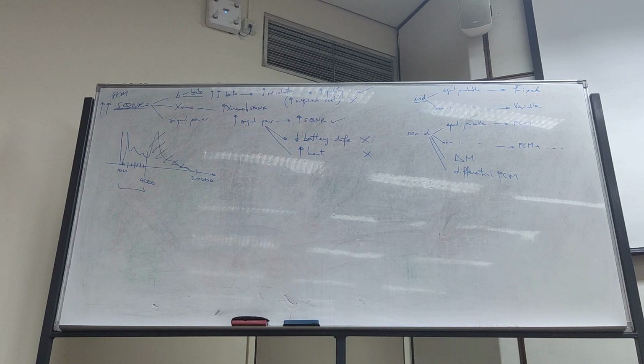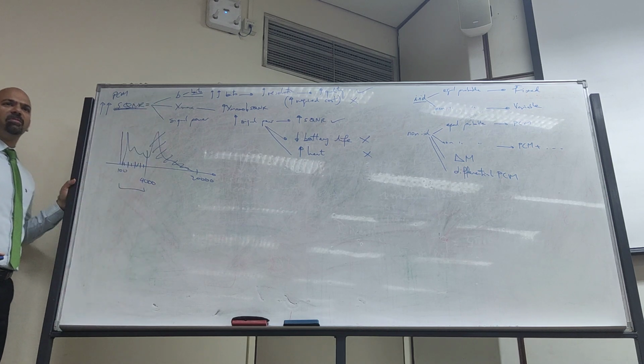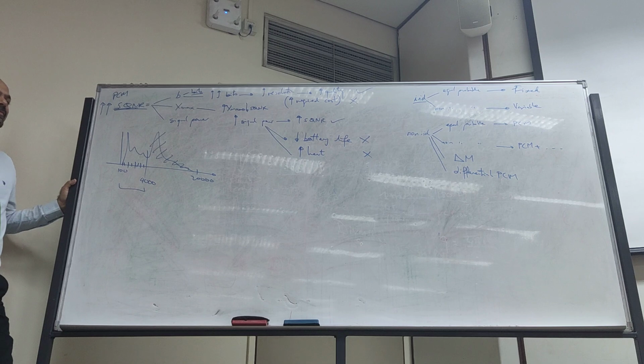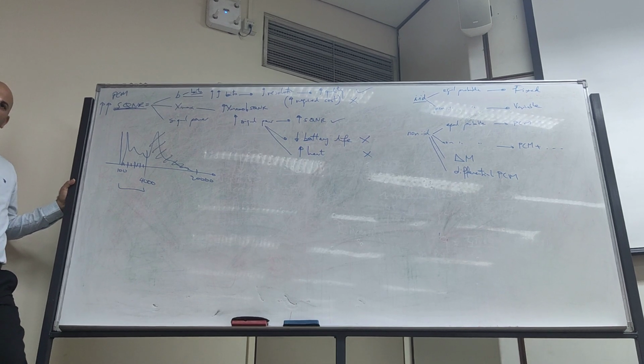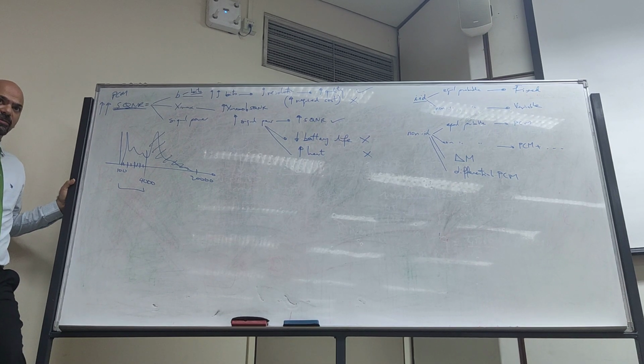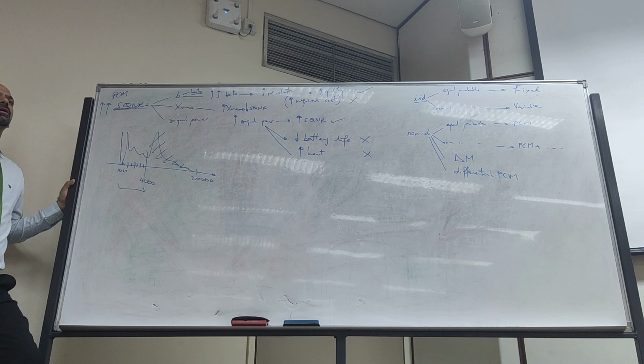So is there a disadvantage for decreasing X max in order to increase the SQNR? Definitely. The nice thing in engineering is that whenever you increase something, you will have an advantage and a disadvantage. So whenever you decrease the X max, what will happen? The quantization levels width will decrease. This is good, but also the error will be increased.